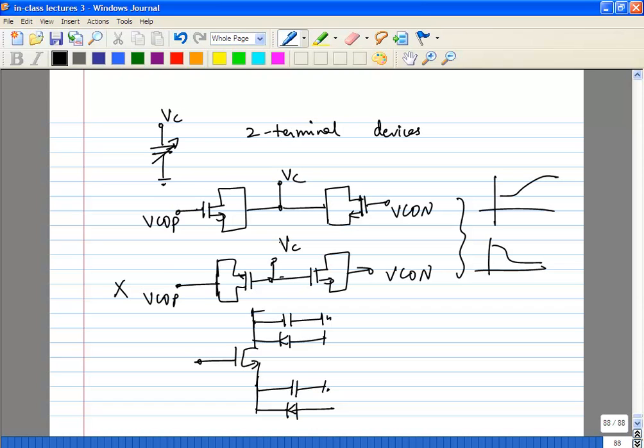That's much better. The second thing, if you look at the Qs, this side you only have the gate. The Q of the gate is very high, whereas on this side, the Q of the diodes and the parasitic capacitances is much lower. So you want to do the first one, not the second one, because unnecessarily you are hurting your Q and hurting, in the end, your noise, your amplitude, everything.